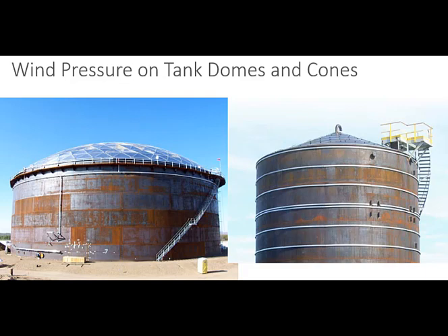Today I want to talk to you about the average uplifting pressure on both dome roof tanks and cone roof tanks. To get an understanding of this requires lots of computations based on ASCE 7-16, which we've done. These calculations will help us move forward in improving API 650, both its clarity and the methodology for computing wind pressures on roofs.